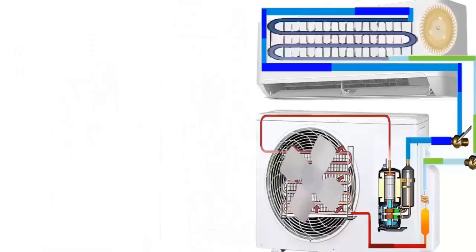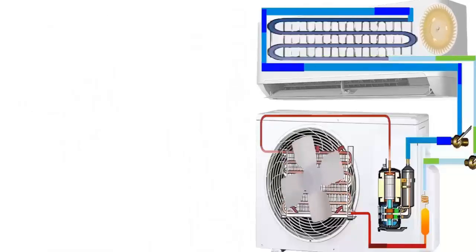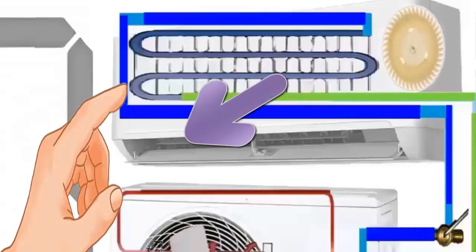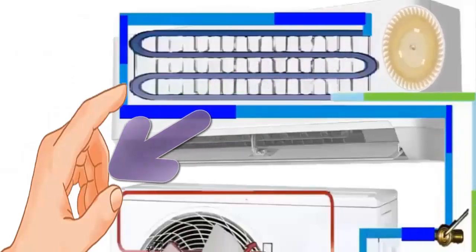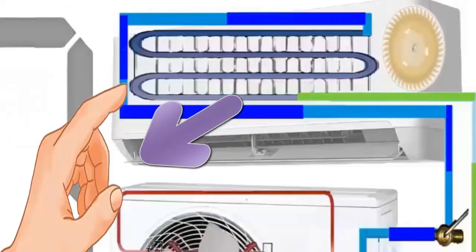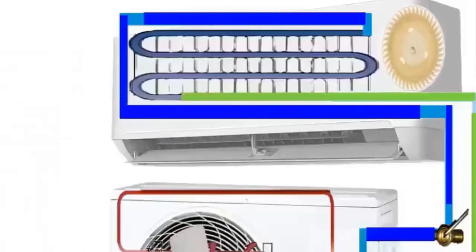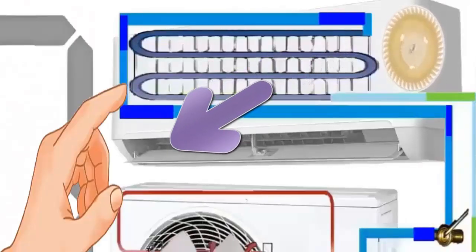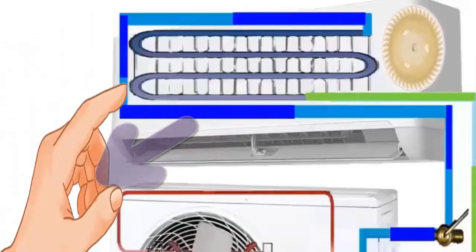2. If the error continues, with the unit turned on in cooling mode, check if the air coming out of the indoor unit is sufficiently cold by placing your hands in front of the air outlet. 3. If the air is sufficiently cold, there is probably no refrigerant leak or lack of cooling, and the problem may be a false alarm.